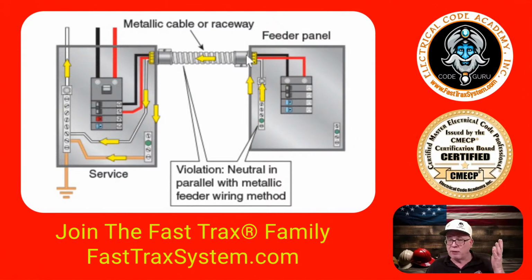And ideally, if this was MC cable, for example, then we would have an equipment ground run with it, running over here to here, and then we would isolate this neutral by taking this green screw out, and we'd be done. Now, some people say, well, Paul, why don't we just use the raceway here? Or in this case, it says metal cable. That's all we need to do because 250.118 says that I can.